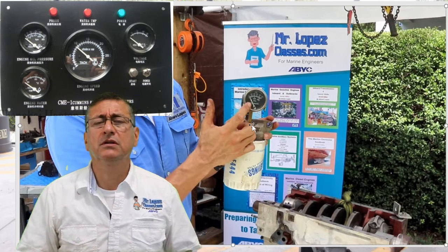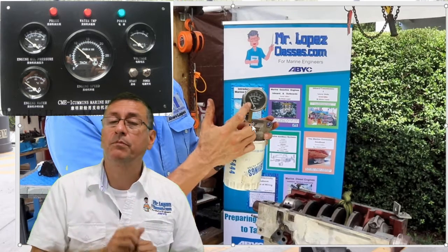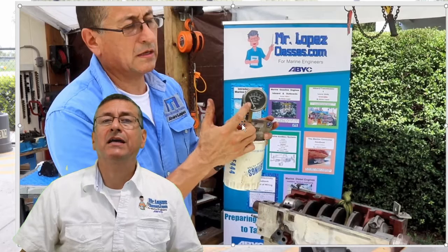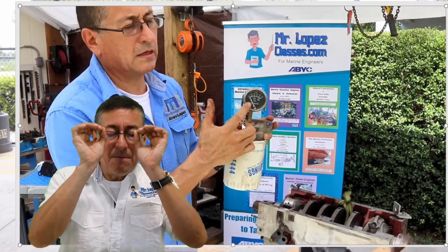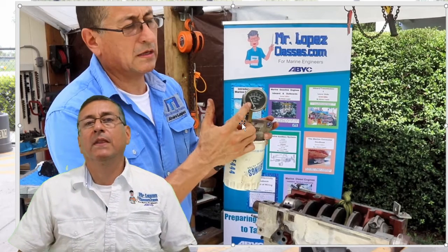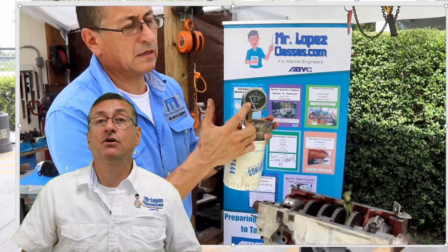This is good. That's your decision. If you want another oil pressure gauge, I love it. Install that oil pressure gauge in the bracket, because the maximum pressure produced by the engine is located at that point. For me, it's a good indicator of the pressure of the oil.